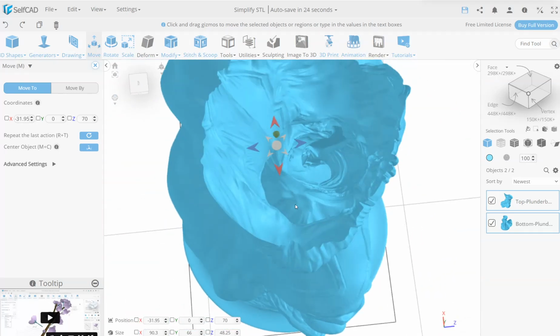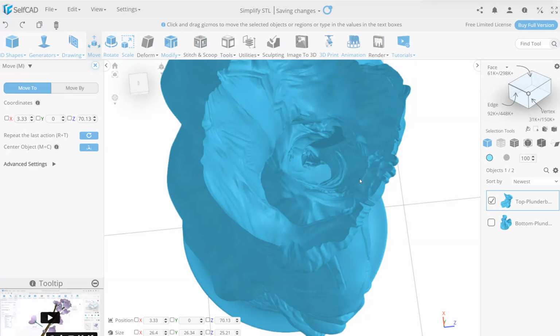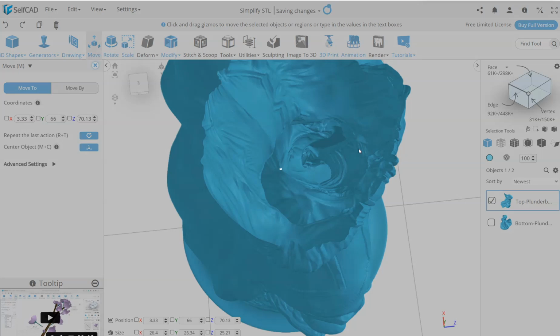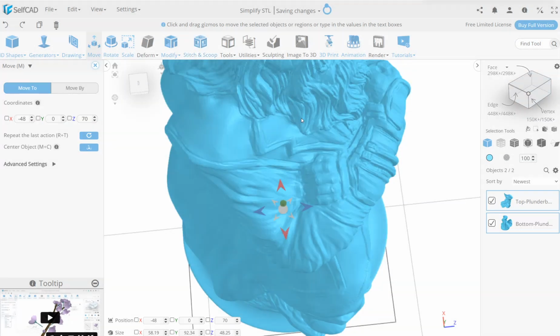However, when you want to make sure that the parts are bonding strongly when you are attaching them together, it is important to add keys on the bottom section of each of those parts, so that it can be easier for you to join the pieces together and make sure that the pieces are strongly bonded. And you cannot add it when it is hollow like this. So you need to ensure that you fill even this top section. I'm going to show you how to ensure that your part is not hollow and it has material on top.